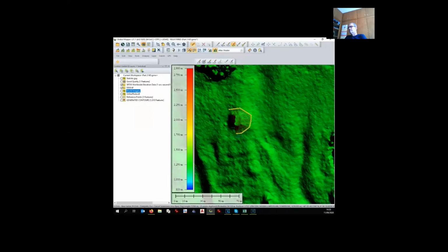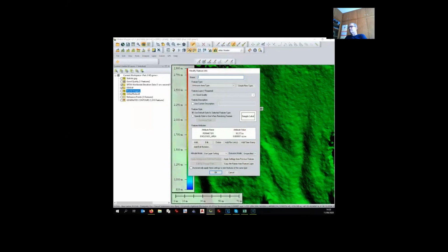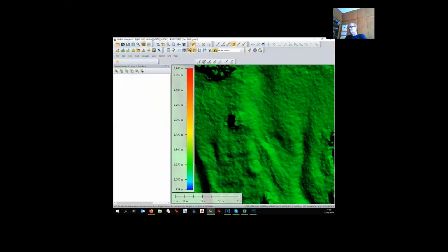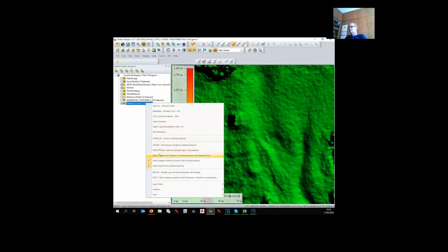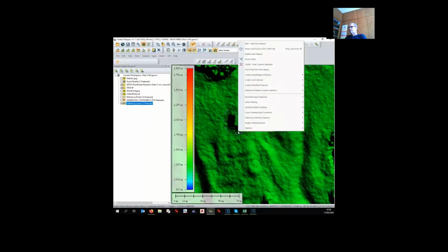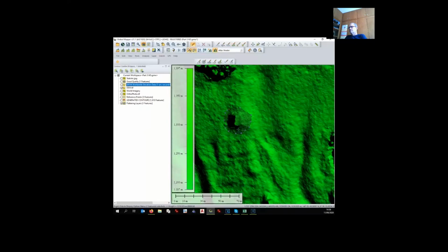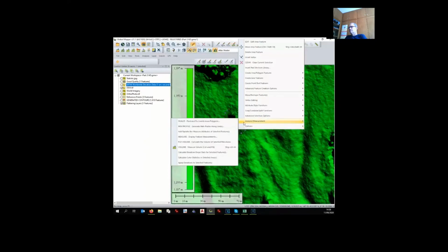We have to create a new area. Ideally, I took out the orthophoto. Create area, so flattening area, flattening. You create a new layer. Okay. Now, this layer does not have elevation. You have to give to that layer the elevation in the same way. You select, you right click on it, take out this one, you right click on it and analyze measurement.